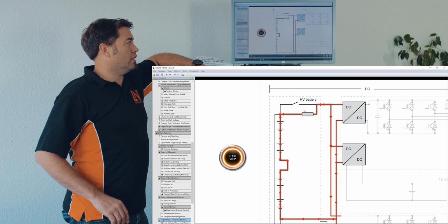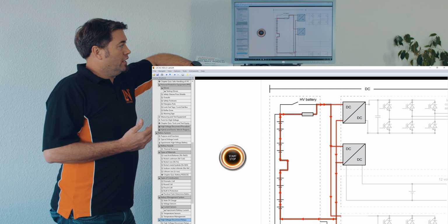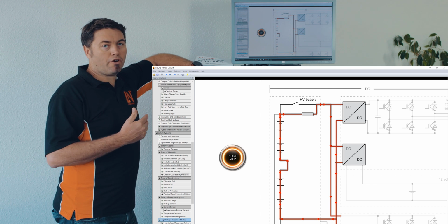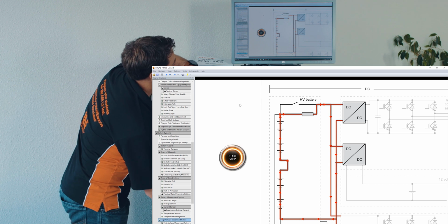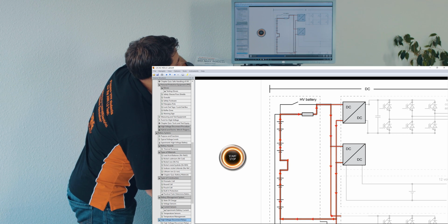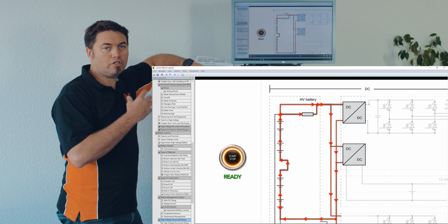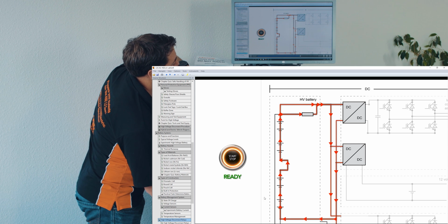That pre-charge relay allows the vehicle to build up the current slowly. And there's a couple of reasons for that, but I'll just continue here. So it allows that to happen first. Once a few conditions are met, it then closes the main relay. And you see there's no resistance there now, so full current is available at the inverter.